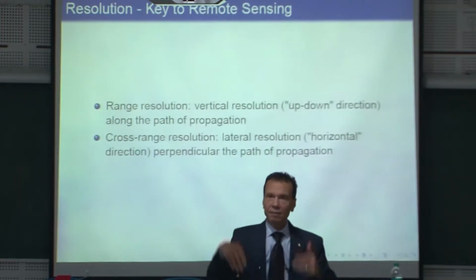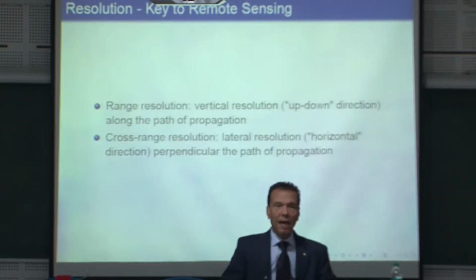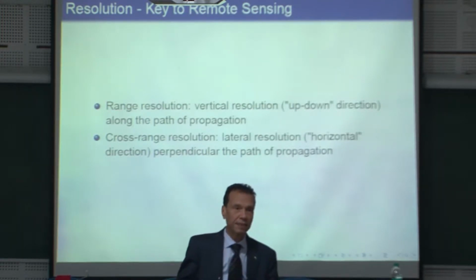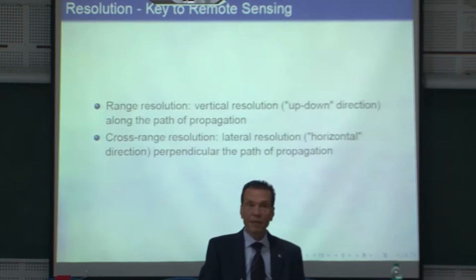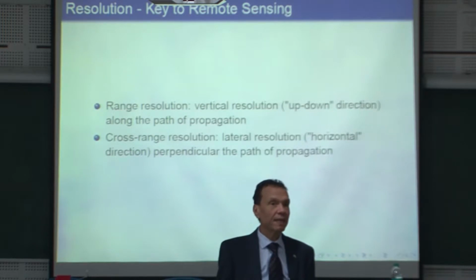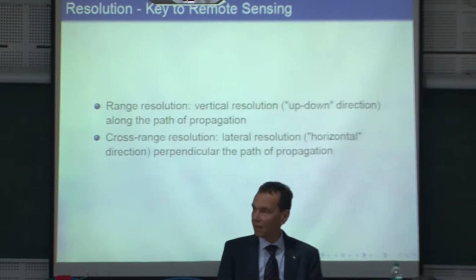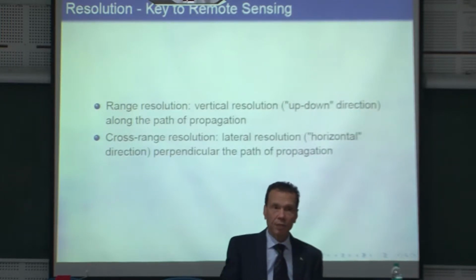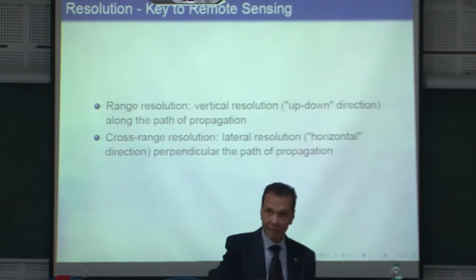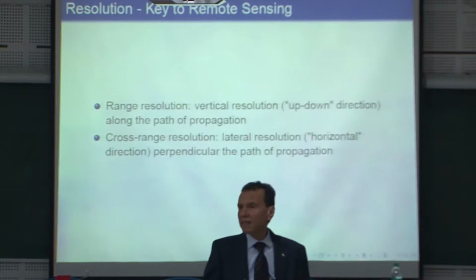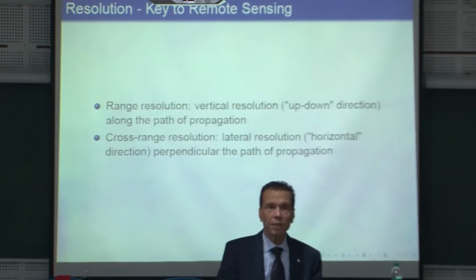I use the bandwidth for the depth, and I use the SAR concept, moving my transmitter and receiver over the ground, in order to have a big antenna aperture, in order to increase the lateral resolution. Now we combine both. We have a three-dimensional image: the wider the bandwidth, the better the vertical resolution. The wider the antenna aperture or the area over which I am scanning, the better the lateral resolution. The concept is clear. GPR itself is just an imaging technique.